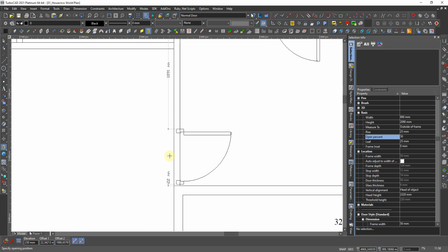You see there, it stands 69 now. I want that to be 100. And if you see down here, on the offset 1 and 2, that is where we can change it. There's 1, 2, 3, and that's the one I want to change. So I tap there and I write 100 and enter.